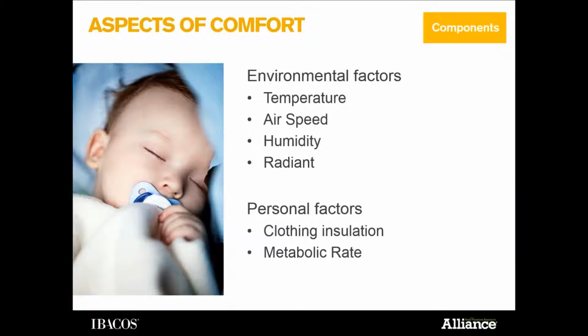And then obviously the personal factors. This is varying on the individual. My wife, she's very fit. She tends to put a lot of clothing on in the wintertime. Versus me, I got a little bit more insulation on my body, so I don't need the sweater. So these come into play. Even within a home environment, we've got two different occupants with two different metabolic rates.